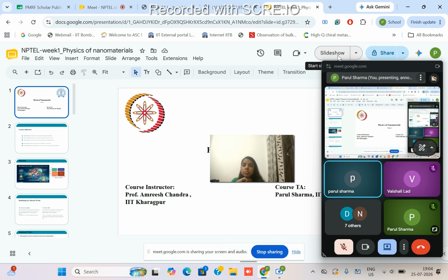Now, depending upon in which direction we are dealing, the properties will change according to the direction. For example, we have carbon nanotubes. So you can see the SEM images of carbon nanotubes, which is known for their high strength and conductivity. So when we see only in a particular direction, it is larger than 100 nanometer. But in this direction and in the height direction, it is lesser than 100 nanometer. So there is an anisotropic behavior. But we will get the high aspect ratio, obviously, and then it is efficient in charge transport.